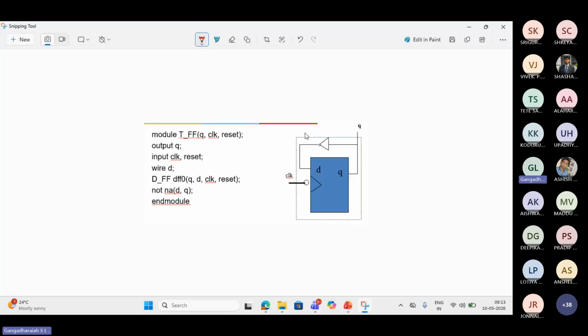That is why, in the next revision, they tried to avoid this, and they defined a new type called logic. Even if you swap wire and reg, that's not a problem. Logic is a new type which is defined in SV. You need not worry too much about wire and reg. Wire and reg are still supported, but you can simply declare it as logic.